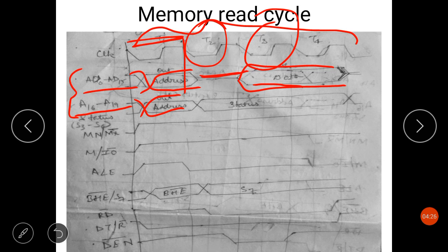During a wait state, the signals on the buses remain the same as they were at the start of the wait state. If the ready input is made high during the wait state, then after the wait state, the 8086 microprocessor will go on with the regular T4 clock cycle.